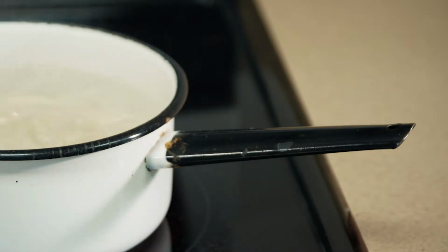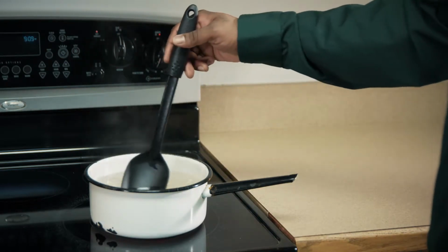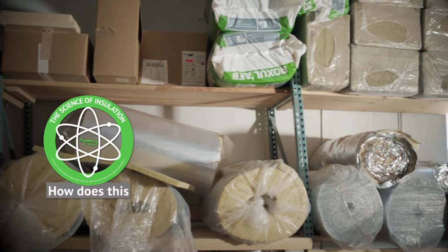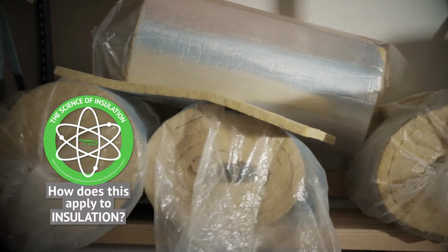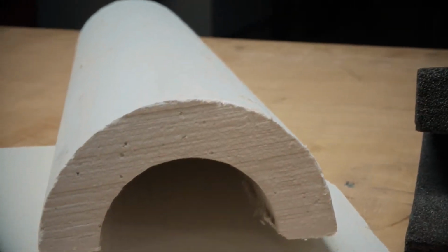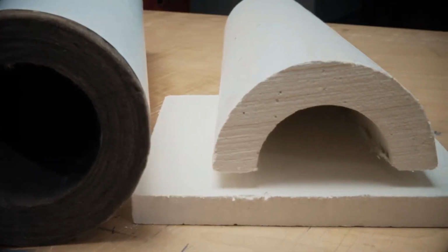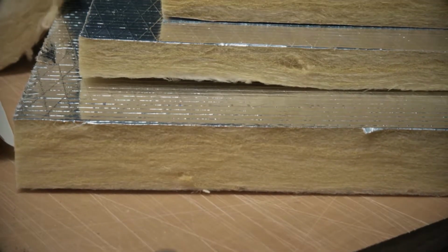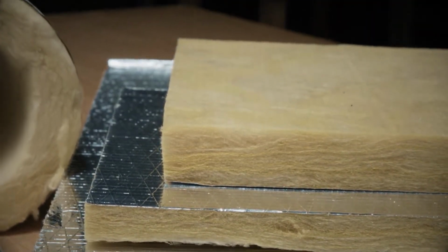A material that does not conduct heat very well is plastic. Using our same example, you can use a plastic spoon to stir the pot while cooking without worrying about the spoon burning your hand. Now, let's talk about how this applies to insulation. Some insulation conducts heat more than others. In high temperature applications, we might use a material like calcium silicate. It does a good job of holding the heat and not letting the heat convect through the material, but it does conduct heat. So, calcium silicate might feel hotter to touch than a fibrous material that is actually letting the heat convect or dissipate through the insulation.